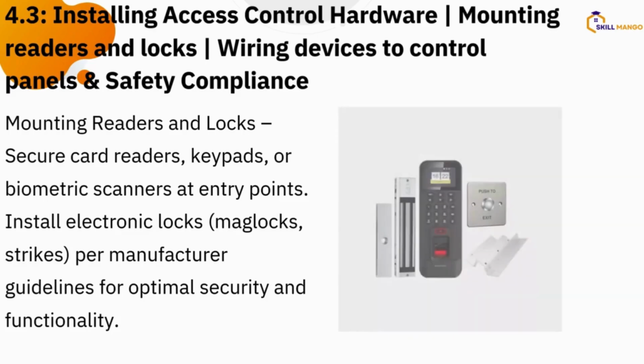So inside is the exit button. At the top is the magnetic lock. So the ideal thing to do is to mount your reader outside. Then you can drill into the wall, so the wire connectivity will go inside, and inside you can put your exit button at that spot where you're drilling, or you move it to a side where it can be easy for one to press it. Okay, so the wiring for the connectivity is not showing, it's inside the wall. You see if everything is there, fit. All right, so from inside the other wire goes up to the mag lock.